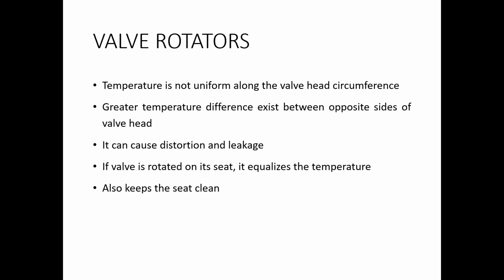Valve rotators automatically rotate the valve after every exhaust stroke. So after one cycle is over, exhaust is over, the valve is rotated at a particular angle before the next cycle occurs.